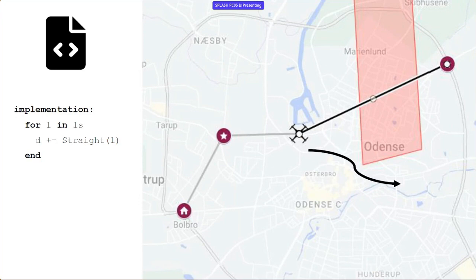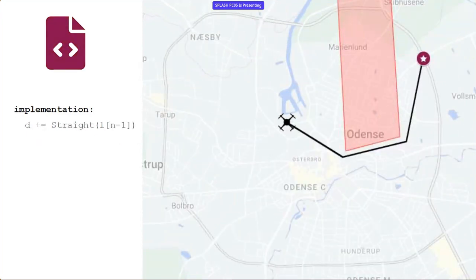What we want to do is to avoid any risk. One possible solution is to restart the mission: take the same program, the same parameters, and compute the flight path again. But that is not replanning, that is restarting the mission. We would start over again and visit the points that we have already visited. And we don't want that. What we actually want is to calculate a new path from a certain point into the future.